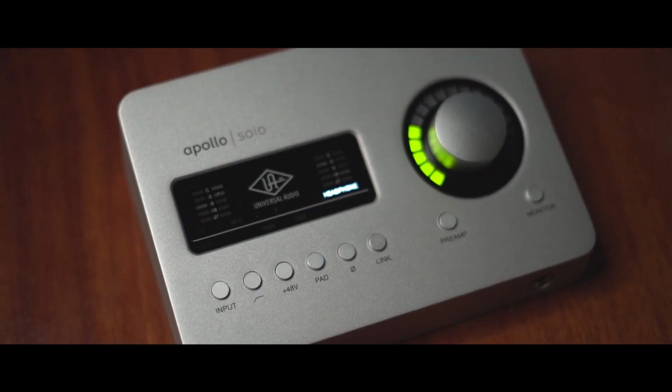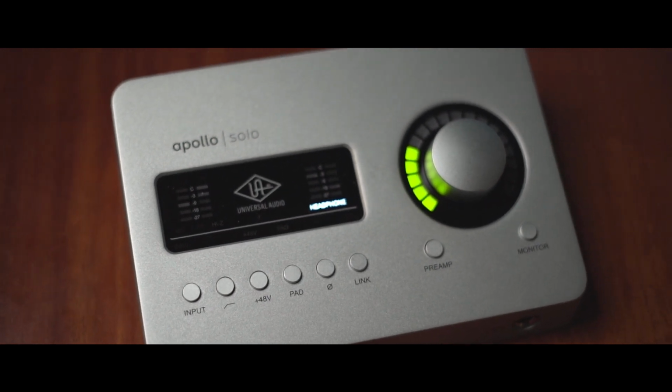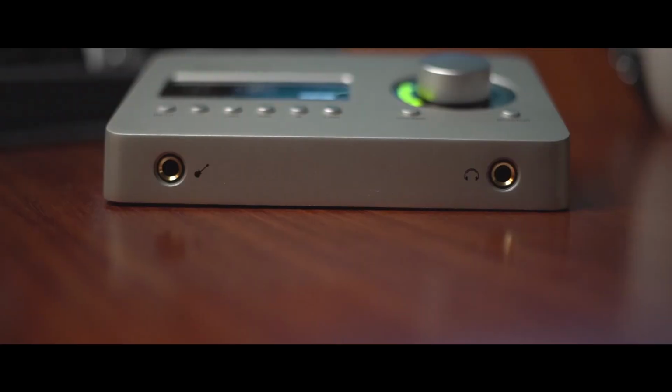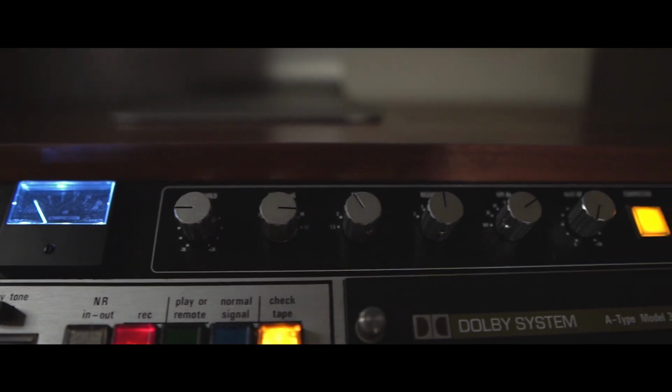All right, so the first term can be found on your Apollo Solo. It's the input button. Now, to go over what an input is, inputs refer to the source of the audio. In a DAW, this usually corresponds to a number relating to the number of inputs on your device. On your device, an input would usually refer to either a high Z jack, a line level jack, or a microphone jack. Now, a high Z jack would be used mainly with electric guitars or bass, so you can plug directly in. Line level is going to be for external hardware, like something like the Warm Audio bus comp. So if you had one of those, you'd take the output of that, plug it into the input at the line level, and then you're going to get a good signal there.